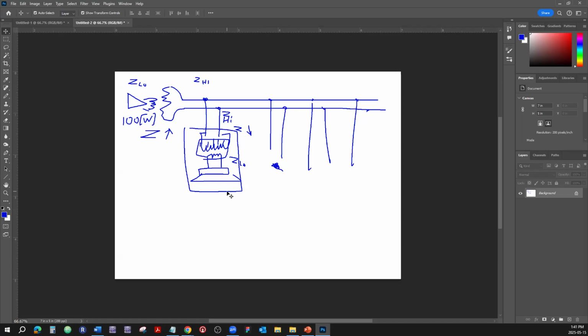You also will have something that's called a volume control if you need it. And the volume controls come with different power capabilities. The volume controls are not like a potentiometer, just like a slider. That's not it. The volume control for this type of system has the dial, and it has one common terminal, and it has a bunch of steps, and you just click between one and the other, and it chooses different taps of the transformer. So there's a transformer at the back of that volume control. I'll show you that when we're in class as well. We have those. We're just not going to use them.